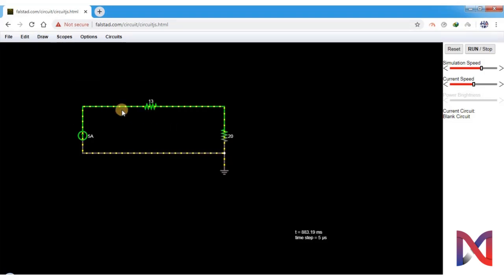So we will select and drag this resistor in parallel. Here it is not connected, so we will delete this wire and click on wire again. Connect both these and complete the circuit. Now we were required to measure our current for load resistance.